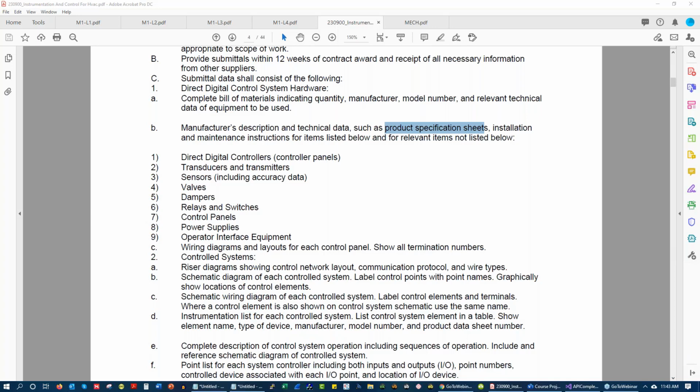Can I review commissioning and how it relates to submittals? Yeah, sure. So there is formal commissioning and then there's informal commissioning. Formal commissioning is where you have a commissioning agent. They're either working for the general contractor or as an owner's agent, and they create a formal commissioning test plan. This test plan will cover how they validate a system is actually functional.